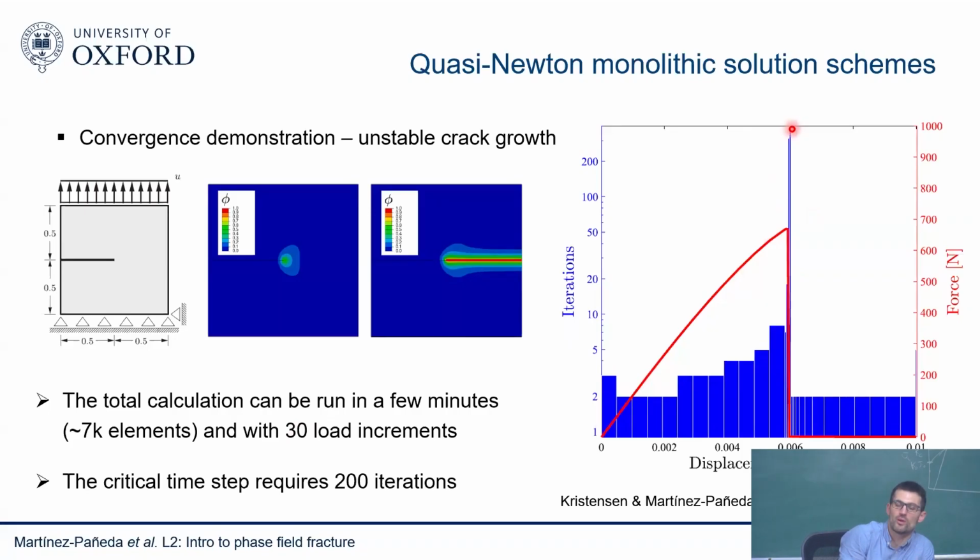And that's something very peculiar of phase field. Because normally, and in fact you need to tell Abaqus, normally with Newton methods, if you don't get convergence in 5 or 10 iterations, then you lose all hope. Newton-Raphson is not going to find the solution. So normally Abaqus will stop looking for solutions at 5. It will just start decreasing the load increment and doing other things. So you actually need to tell Abaqus, hey, give it a bit more time, because it may find it.